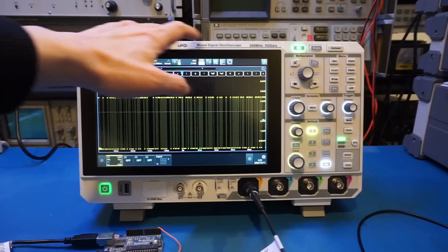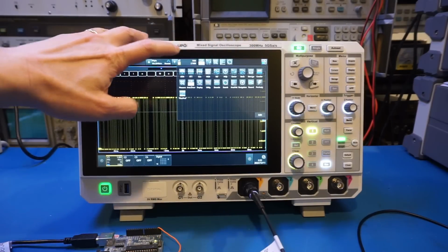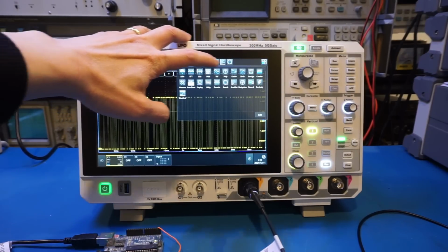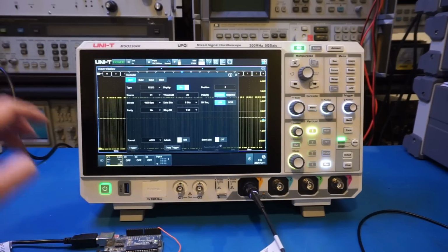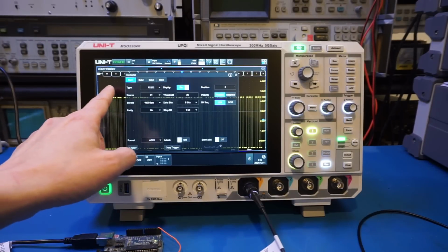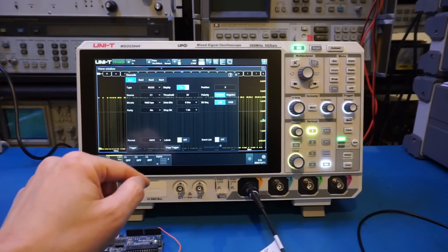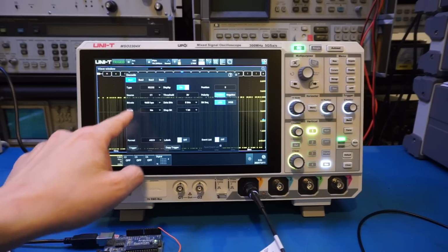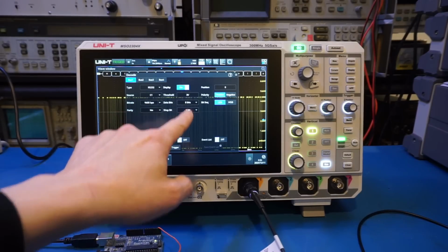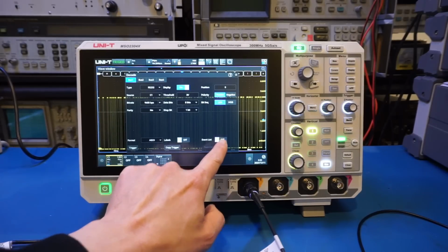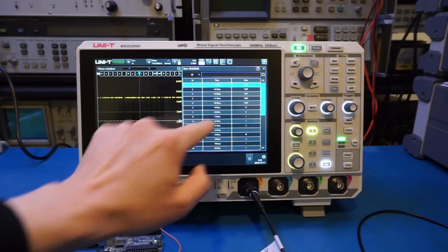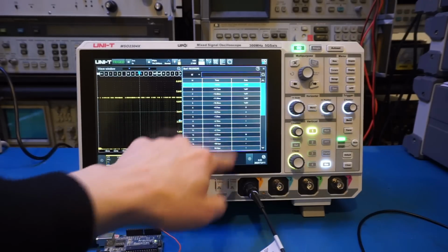Now let's take a look at the protocol decoding side. So I come here, decode. You can see here, again, we're setting up as RS-232. And we also have a bit rate of 9600, 8 data bits, and 1 stop bit. So that's the data we're generating from the Arduino. Of course, I can also enable the event list that will show us the decoded symbol here. You can see that. That is our hello world.